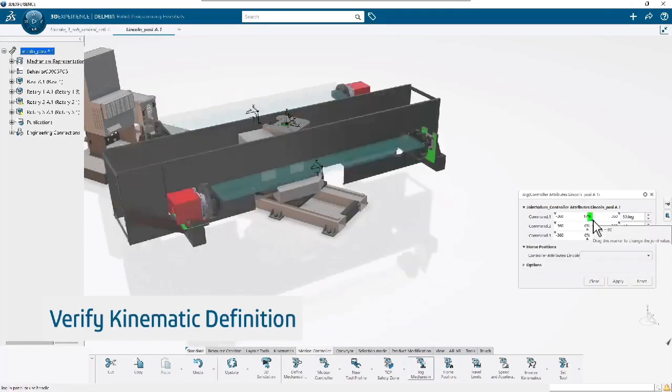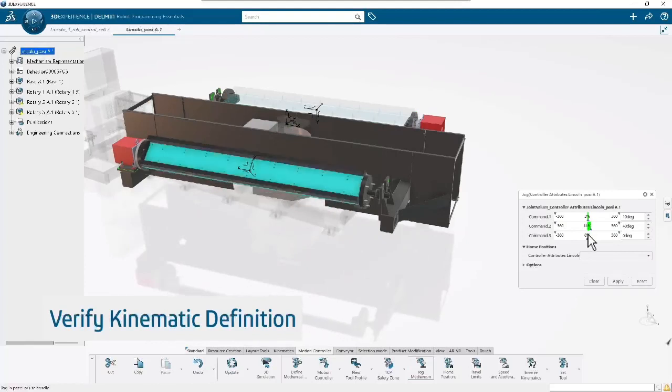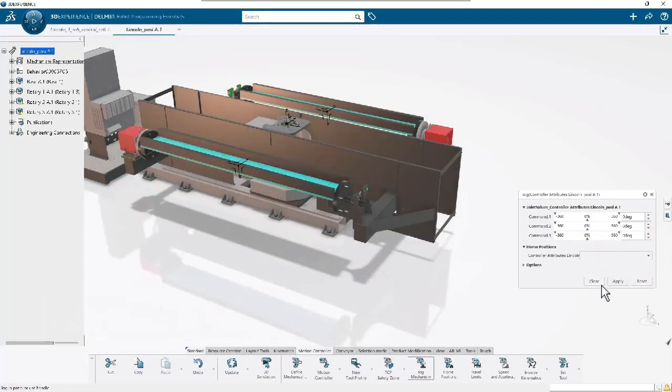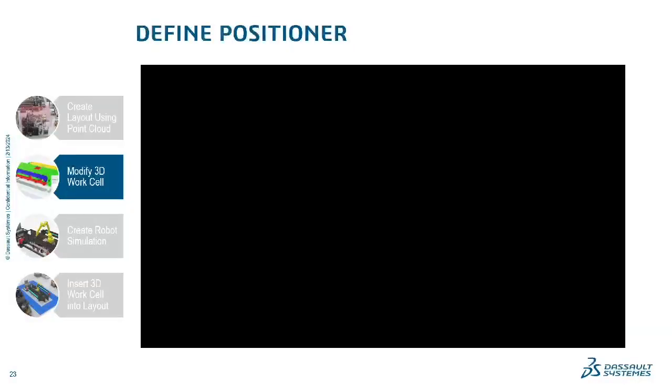And so if I've had those labeled correctly, I know which access systems I need. And once I define everything, I should check my kinematics. And I really, really strongly advise you to check your kinematics because I've definitely defined things and had things fly into space after I was done, especially with the old way of doing it.